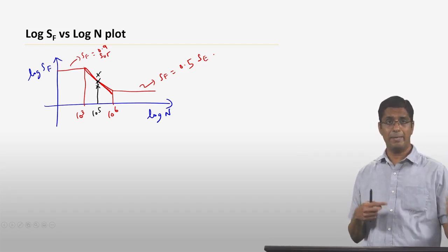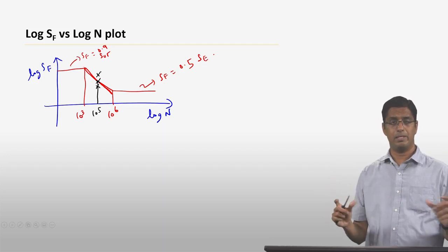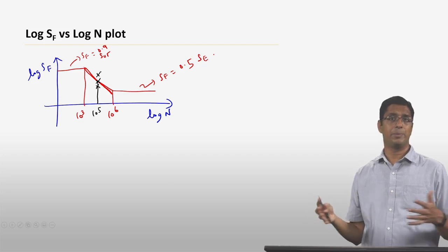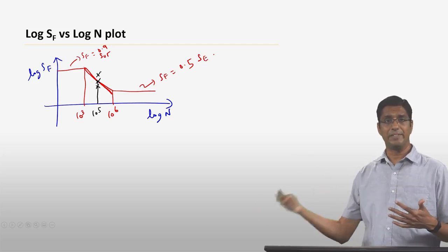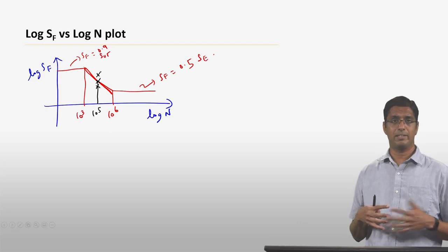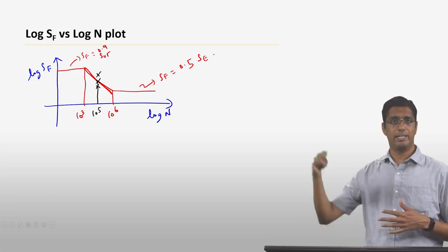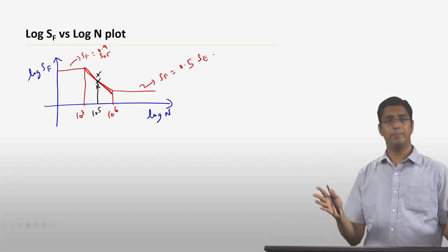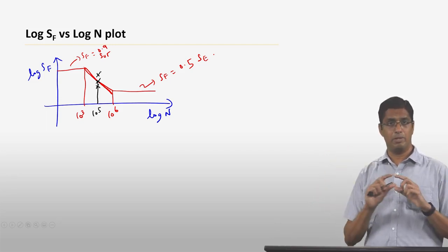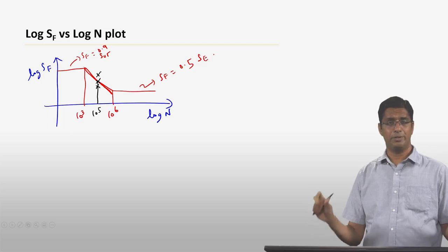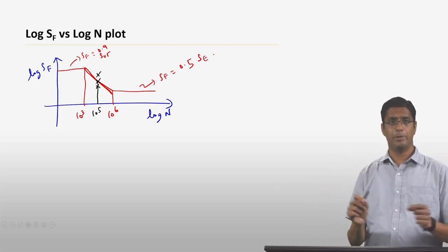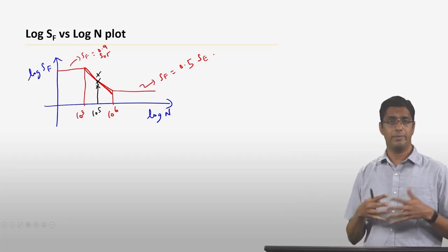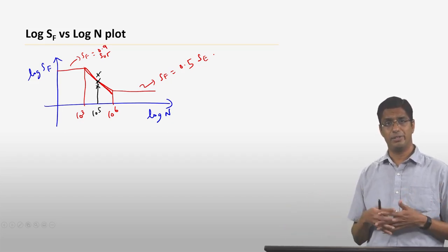If you apply the same stress on the same kind of specimen in 5 different experiments, in one case you might have the specimen fail in 15,000 cycles. In another one, it might fail in 14,200 cycles. In another one, it might fail in 16,000 cycles. So if you take the same material, the same nominally identical sample, and you use the same boundary conditions, you apply the same load, you're going to have a variety of number of cycles where it's going to fail.